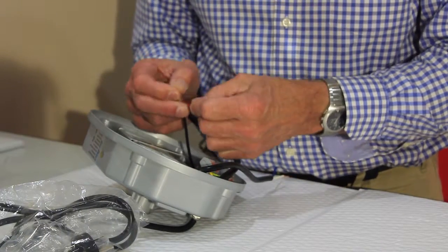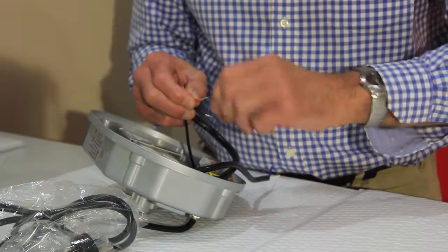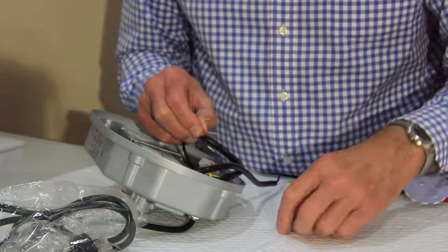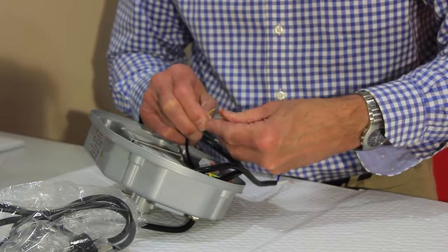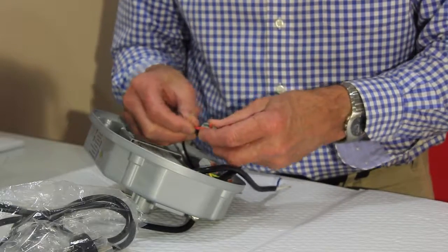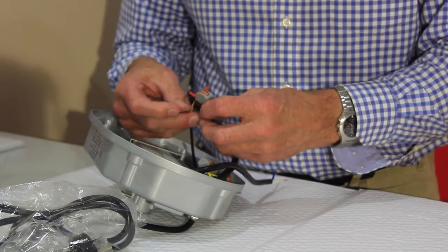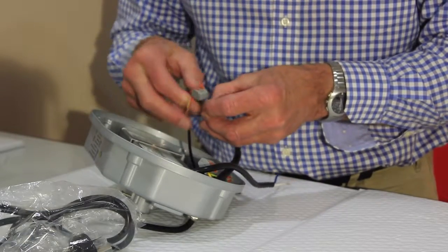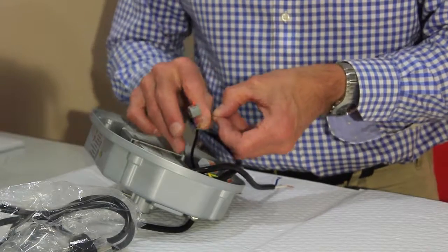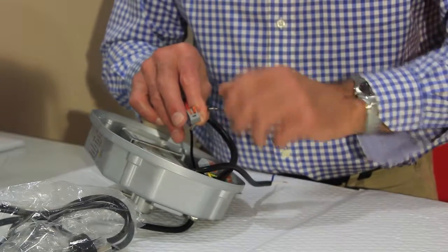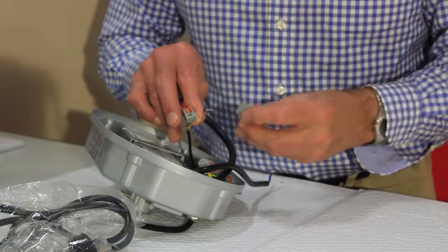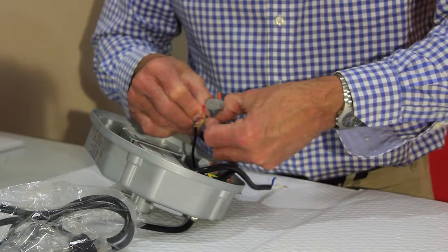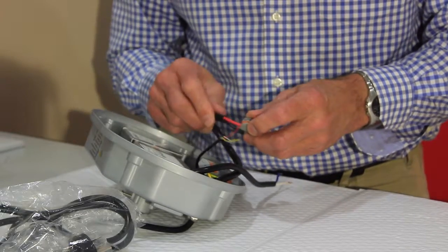We're going to pick that up here with the control cable. The controller needs to have power as we discussed before, so we'll just wire that up. We'll use a quick connector to put it together. That's not the best way to do it. It should be soldered. That's strong enough there. Take the black around underneath like that, and we'll wind that around there like that and pop on a quick connector there and lock that down. So we've picked up our 2 lots of power.